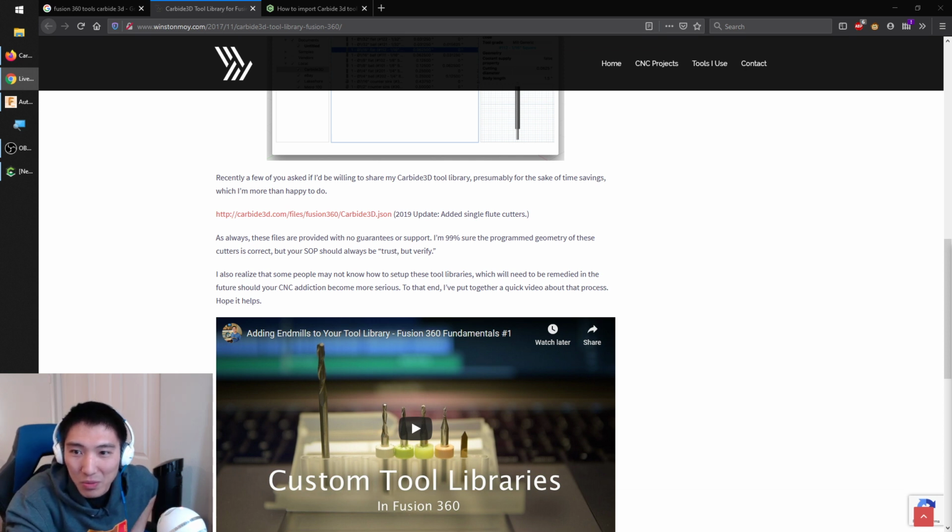What's a good end mill for making holes in 2mm aluminum with the Nomad? I would say a 16th inch end mill, 16th inch being just under 2mm, which is like 0.079. And then use a boring operation if you're using Fusion, or just do a really shallow depth of cut pocket or contour in Carbide Create.